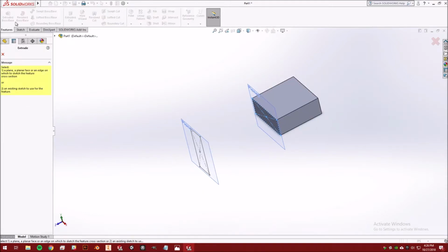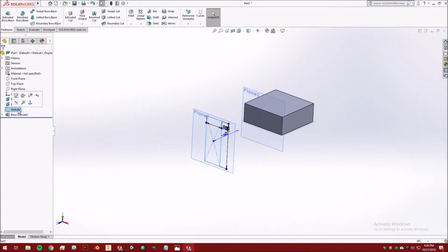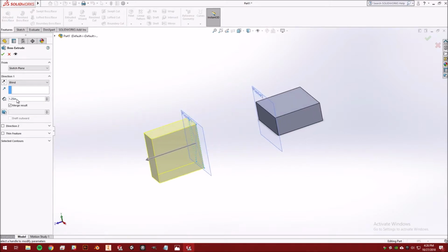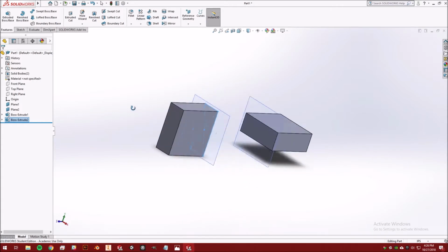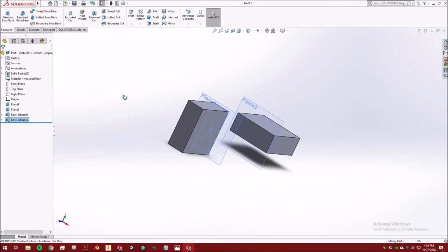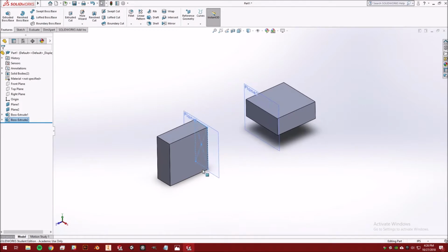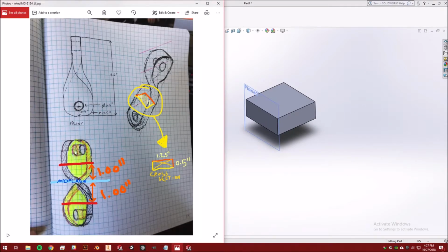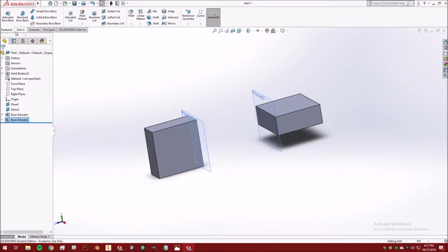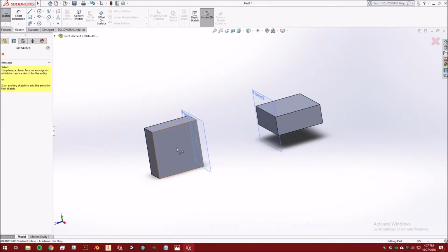Let's go ahead and do the same thing for the other half. Make sure we select this sketch, Extruded, 1.25, that's correct. Alright, so now I've got two perpendicular little rectangles here. And for each half, we're going to want it to look more like these curved shapes for the bracket with a hole drilled into them, and that's pretty simple to do. We'll start with the hole, so we'll create another sketch on the surface of this model.